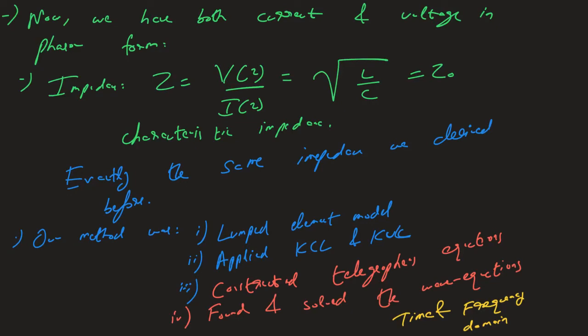So I've taught you how to solve these in time domain, which is what we did last time. We just laid down our differential equations as functions of position and time. We decoupled them into our classical wave equations. We took a forward propagating solution, and then we solved. Today we looked at the phasor notation, and then we built upon the phasor equation and did the same analysis.